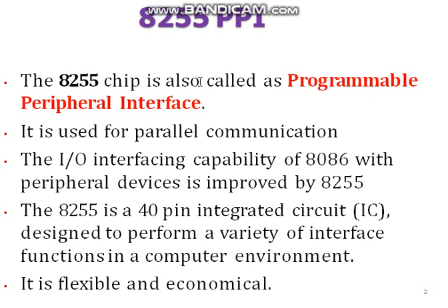The advantage of using 8255 is that it improves the interfacing capability of the 8086. It makes it very easy to communicate with your input-output devices with the help of this IC. The 8255 is a 40-pin integrated circuit, and you can interface many different elements or many different systems with your microprocessor. It is also flexible and very economical.